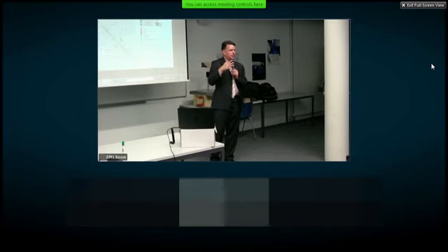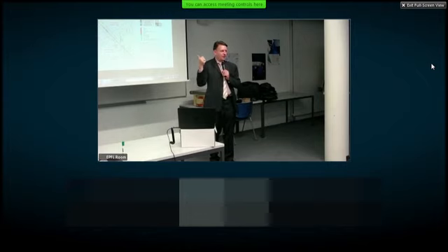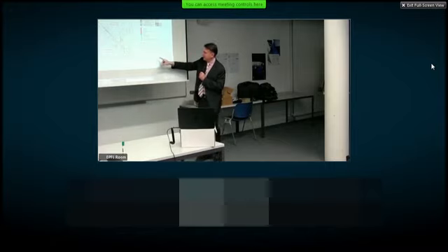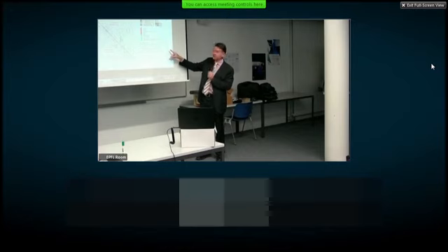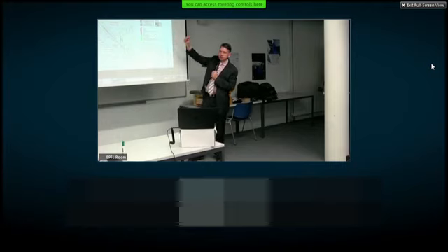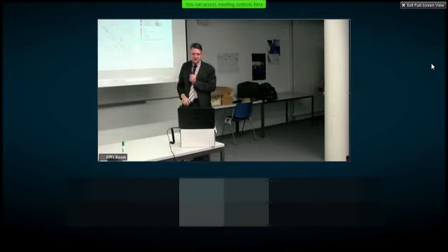So the machine has been decomposed into 84 really subsystems, because you have a lot more than 84 parts. But at this level of abstraction of 84 by 84, we have a total of 572 physical connections, 45 mass flows, 167 energy flows, and 165 information flows. And there's a little more detail here in terms of the types of flows. So in red we have mass flows: paper, toner, air, ozone, and dirt, right? Because you've got to keep dirt out of the printing engine, which is shown here in the middle.